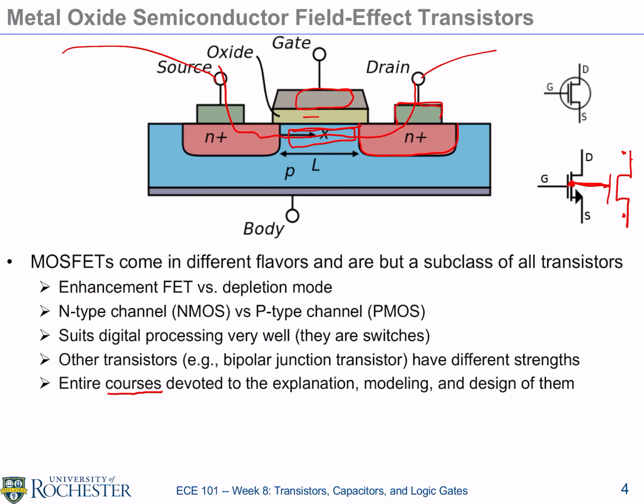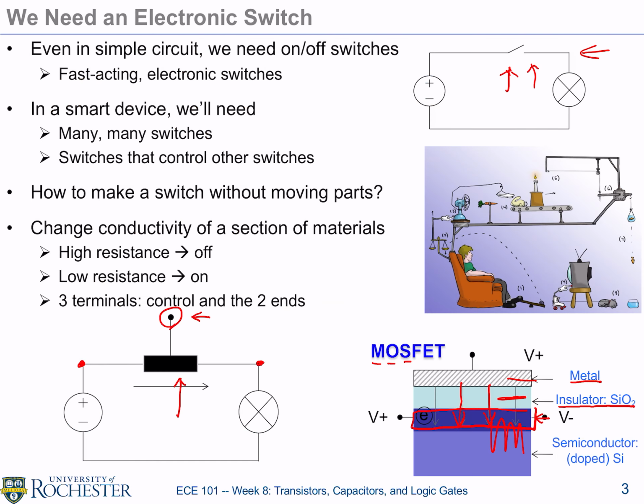In the ideal case, we call them a switch, but they're not really a switch. It's a semiconductor device, so the channel is not completely conducting like a piece of ideal wire, or completely shut off. When they're conducting, in fact, there is resistance. When they're not conducting, in fact, there's still current that we don't want. It's called leakage current.